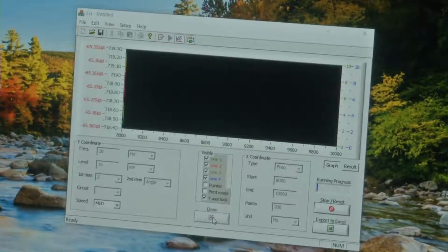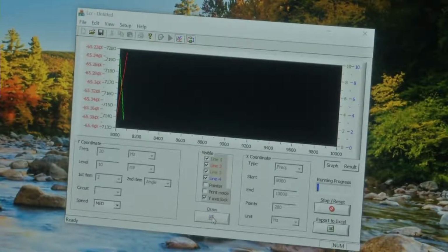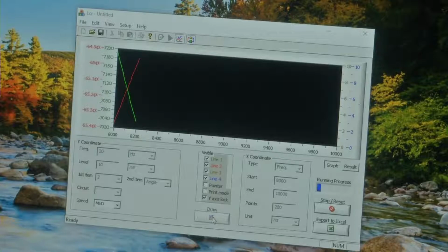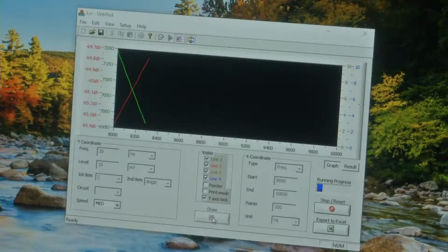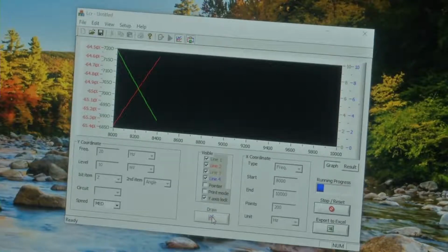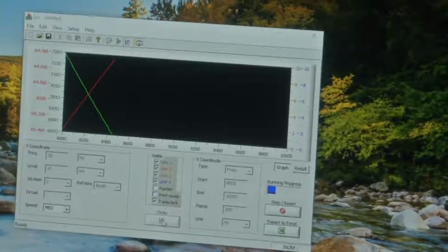This decision we can make only after doing a first sweep of the frequencies and see that where it is changing. So, we saw that there is a sharp fall in the value, and so we are going to look at a more interesting frequency range. So, now we are plotting the impedance and the phase information from 8 kilohertz to 10 kilohertz. It will acquire 200 samples and then we will see.